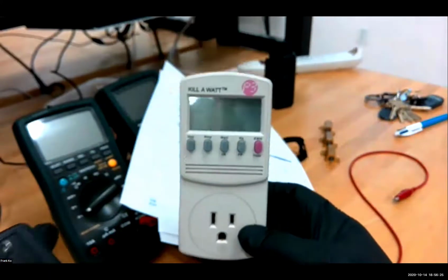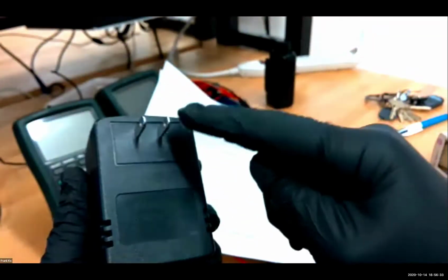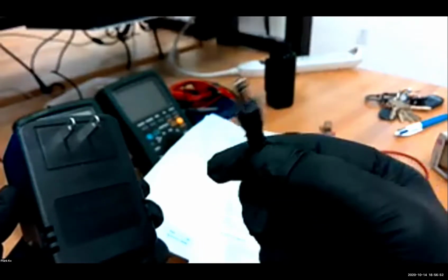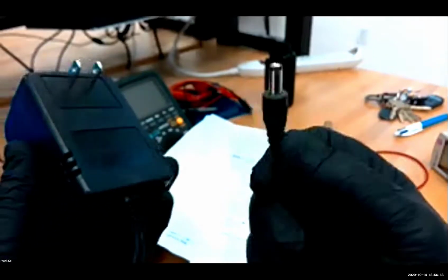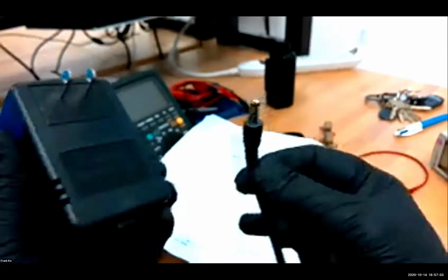Fundamentally, as you go through different steps, you will be asked to use your digital multimeters. You're going to be asked to measure the ohms of the primary, and the ohms of the primary are attached to these two prongs right here. And the ohms of the secondary can be measured on the output side, which is this plug right here. Very often, this is what you're going to plug into your electronic keyboard. This is what you could be plugging into your Nintendo gaming device. It's a very standard wall-wart power supply apparatus.